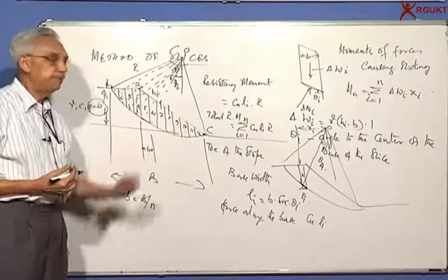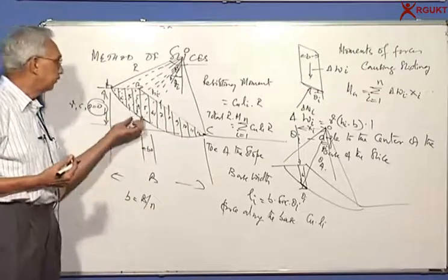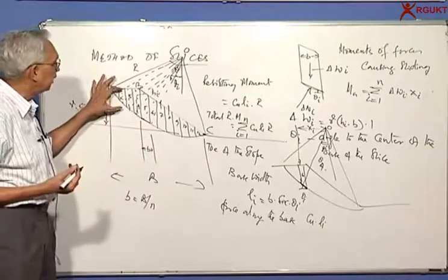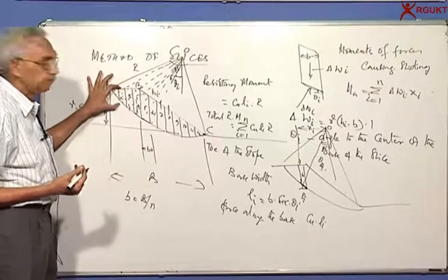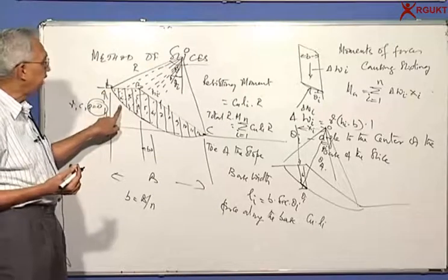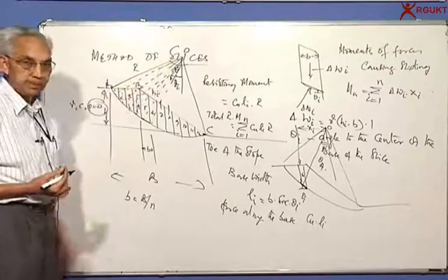So instead of doing all the trigonometry, etc., by dividing into a number of slices, you find out each slice, and with the geometry being known, I need to only know the height of the midpoint of the slice and the angle the base of the slice makes with the vertical.